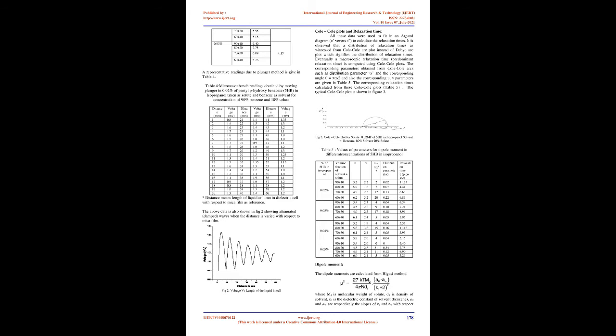In the cavity perturbation technique, the signal obtained without and with sample is fed to the CRO from the tuned detector, which is shown in plates 3.1 and 3.2 respectively. The measurement of dielectric constant and dielectric loss is made. Standardization of the cavity technique.